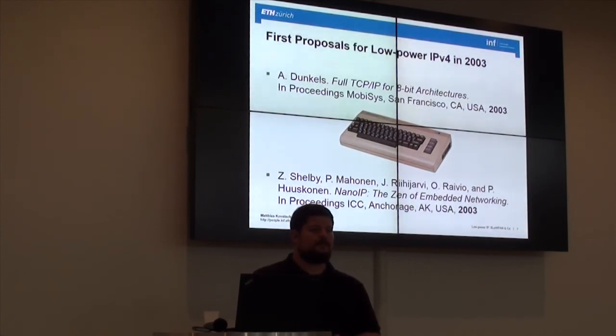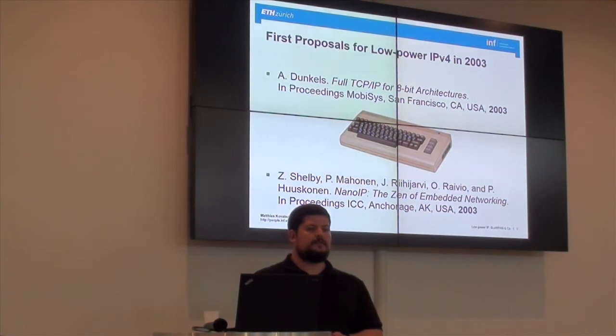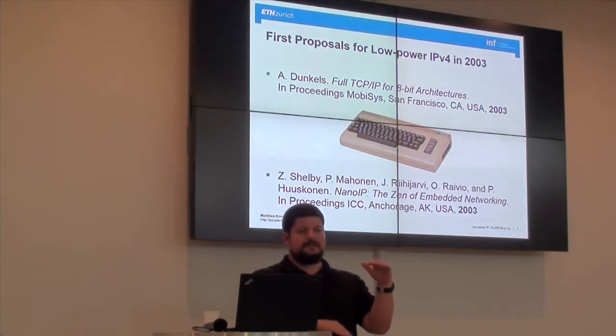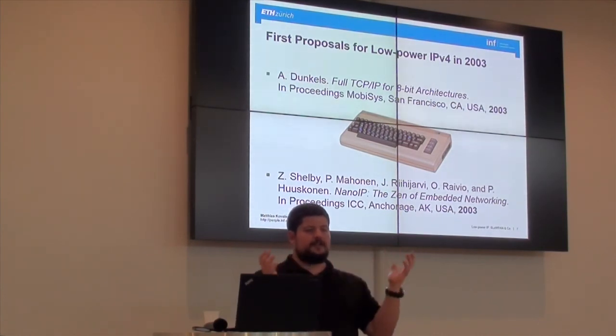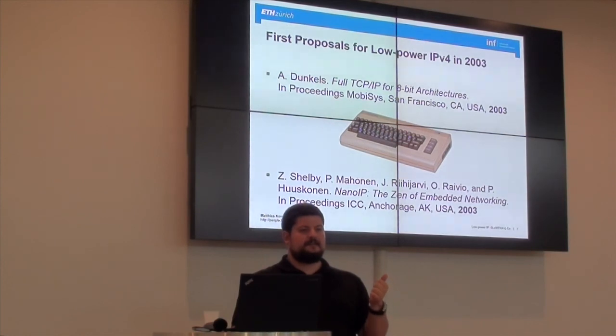Okay, and do you have an idea of the size of the application in the embedded device? Yeah, well, it works on a T-Mote Sky, which has 48 kilobytes of ROM. That's the full IP stack and application and a few application resources. If you take the full functioning CoAP implementation from Contiki, for instance, you are at a rather large 10 kilobytes. The thing is, it really implements everything, every option, and it spends like 3 kilobytes, I would say, on convenience, a RESTful-framework-looking API where you just implement resource handlers, and then you don't have to care about the rest. That's more expensive, but you can boil this down to a few kilobytes CoAP implementation.